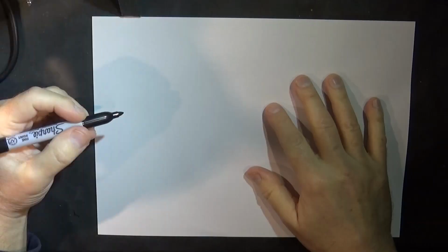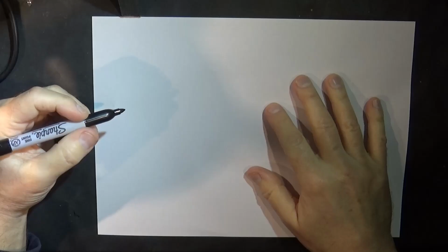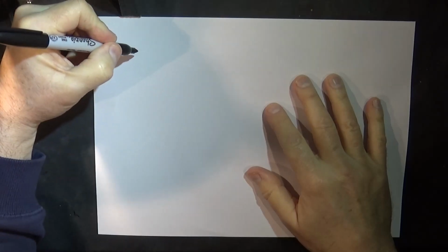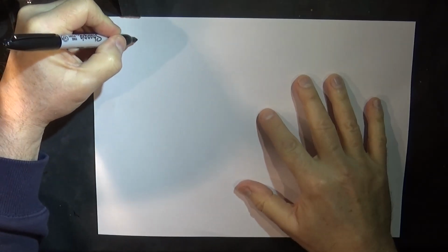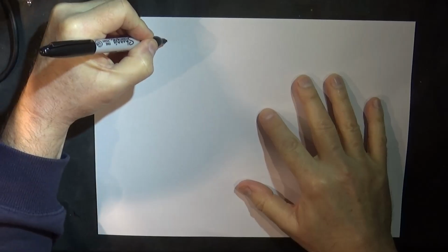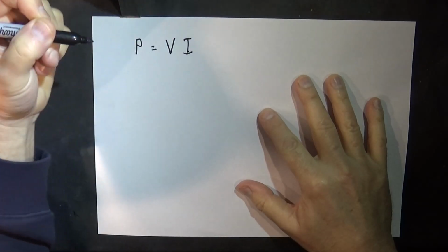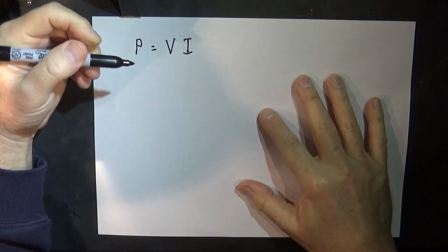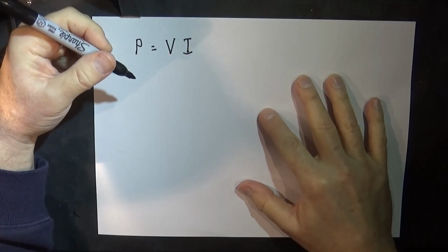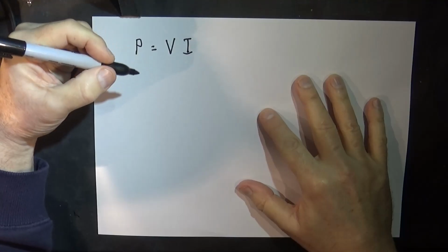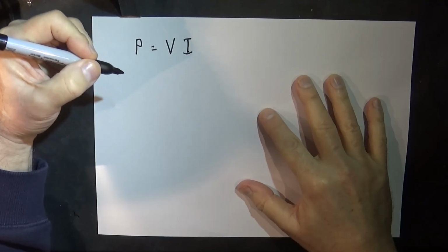And the second problem is to do with Zener diodes, the nature of them and the job they do, and it's a problem I always anticipated happening and hoped I'd work around. Okay, so power equals voltage times current, and we want to know the current we should put through this Zener to get it working in its working area.